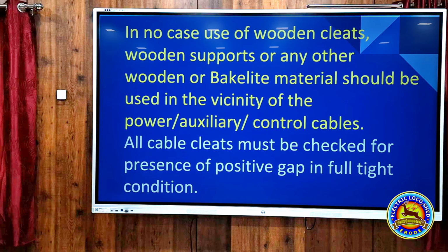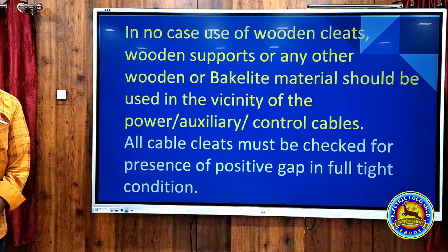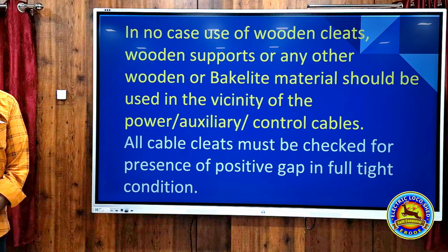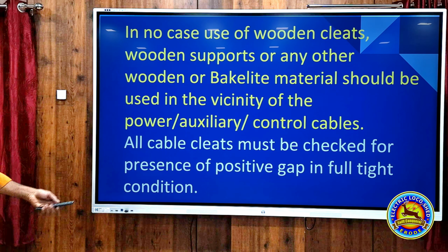All cable cleats must be checked for presence of a positive gap in full tight condition. That is, there should be a positive gap: it should not be too tight, but it should not be slack also. The cable should not move freely, that is, the cleat should hold the cable but it should not be too tight to damage the insulation.